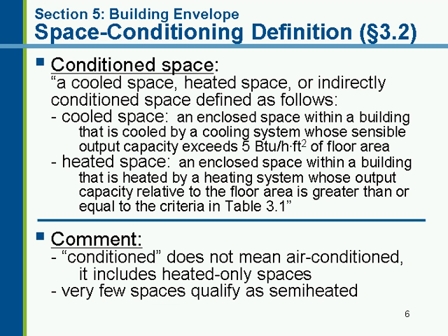Now, cooled space is any enclosed space within a building that's cooled by a cooling system with a sensible output capacity exceeding 5 BTUs per square foot of floor area. So it's about 1.5 watts per square foot. But the key thing here is it does not refer to design loads. This refers specifically to the output capacity of the equipment. So it's meant to be something very easy for designers, plans examiners, and inspectors to check. You simply take the capacity of the equipment, divide it by the square footage that it's serving, and you can see whether or not you're over the 5 BTUs per square foot.